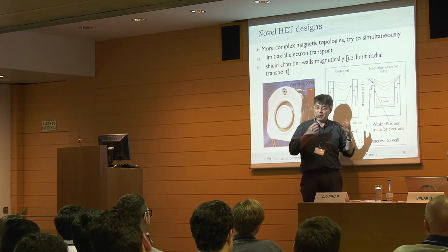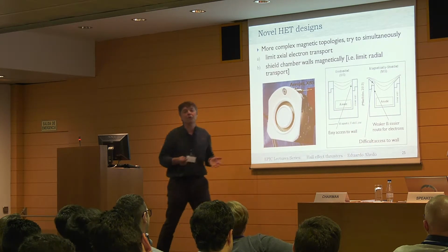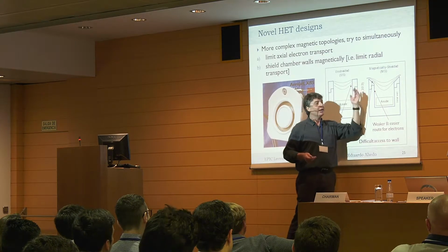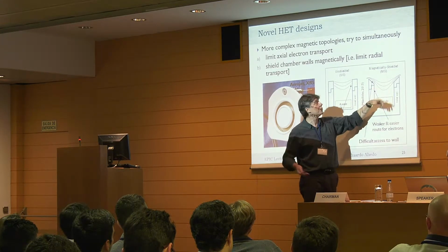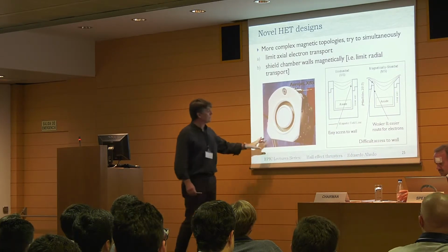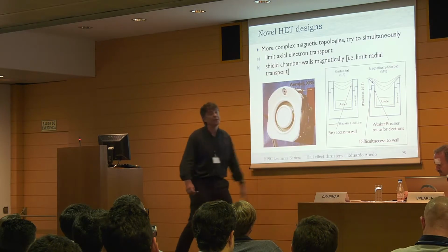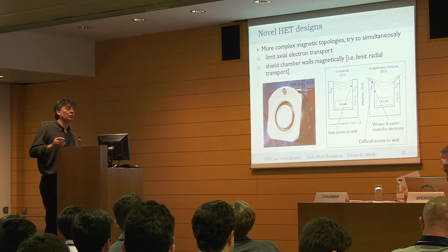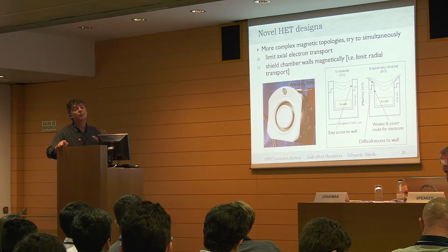So in this way, the experience of the experiments with the new magnetically shielded thruster has been positive for that. We are able to reduce very much, by several orders of magnitude, two or three orders of magnitude, the erosion on the walls. Okay, and this is the most successful thruster in this aspect. It is the Aerojet X5. Okay, it's a 5 kilowatt thruster, and for the moment it is the reference thruster for this magnetically shielded thruster.